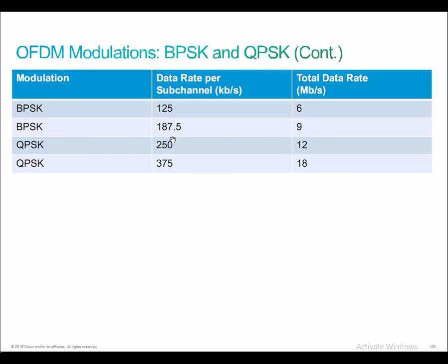QPSK is essentially like a reversed DQPSK. All right. But why would I use one instead of the other? Some people consider the differential method to be more robust than the non-differential method that we saw with DQPSK. Obviously, we can see from a bandwidth perspective, there's a significant difference.